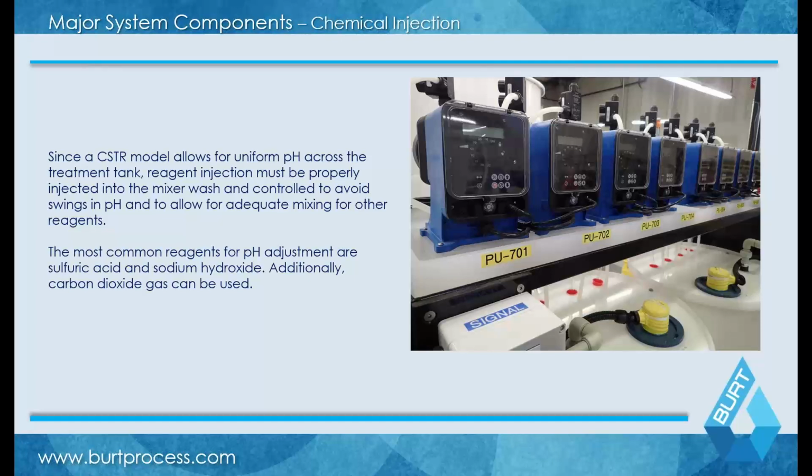Me personally, I think it's better to go with onboard chemical tanks and then have a chemical or trusted supplier actually just come and deliver them. They have the proper equipment, rather than having the facility themselves wheel drums in and out of the actual system and then do the actual chemical handling. It really takes up the same amount of space overall in the system. But your chemical tanks here are fully contained. You don't have to worry about using things like pallets or other equipment adjacent to your system to locate your drums on or lift the drums into the actual system.